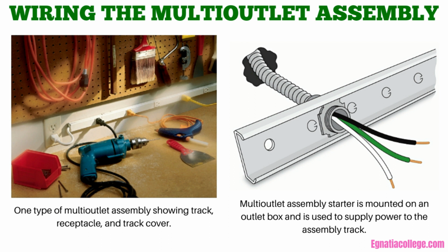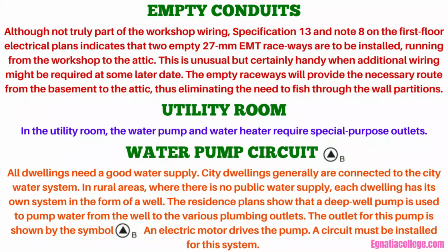In general, multi-outlet installations are simple because of the large number of fittings and accessories available. Connectors, couplings, ground clamps, blank end fittings, elbows for turning corners, and end entrance fittings can all be used to simplify the installation. Empty conduits.